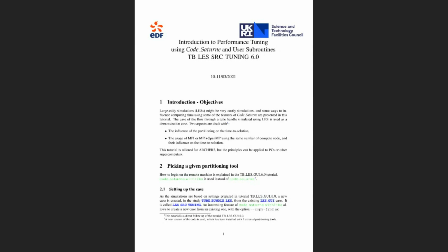But there's also a feature based on OpenMP, which is used, in the case of shared memory, for instance, on a subdomain, you can divide the subdomain in a few threads. And hopefully, when you combine MPI and OpenMP, you can get some speed up. But this is extremely machine dependent, and is also configuration dependent.